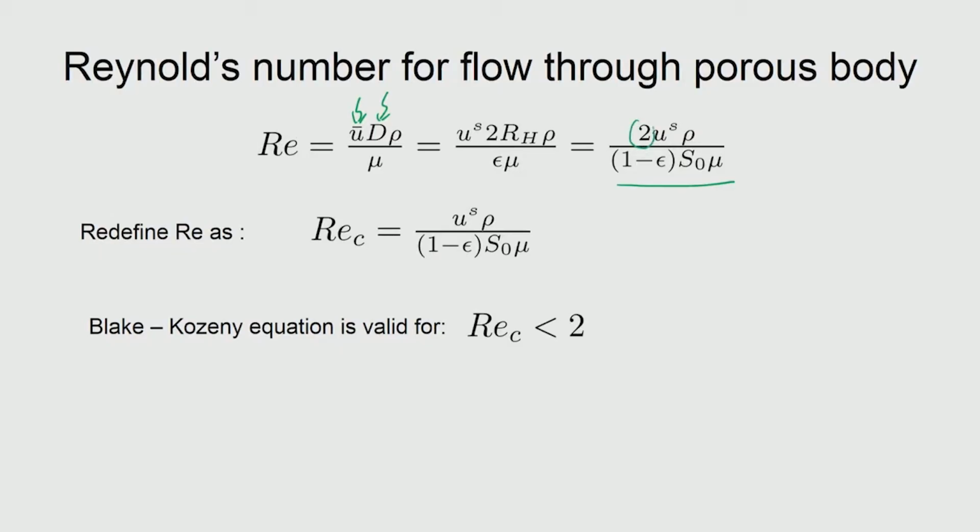Normally, when we have non-dimensional quantities, we do not want numerical things in there, because there is no point in that. We can look at the introduction of non-dimensional numbers as only a way to remove the dimensions, so numerical values need not come. So, we redefine the Reynolds number in this manner by knocking off the 2, and to remind us about the redefinition, we pay attention to the subscript, which tells us that some redefinition has happened.